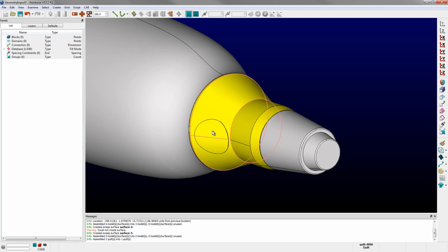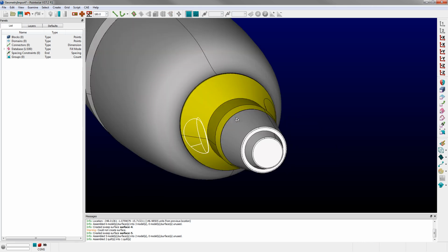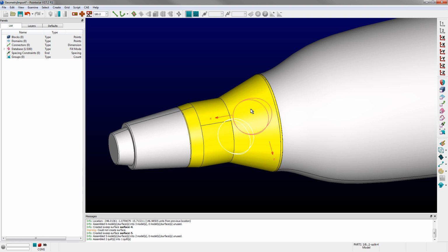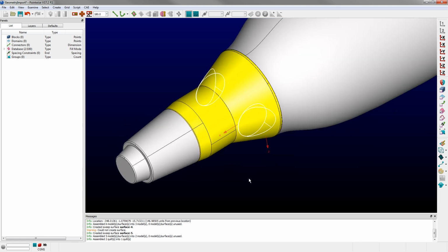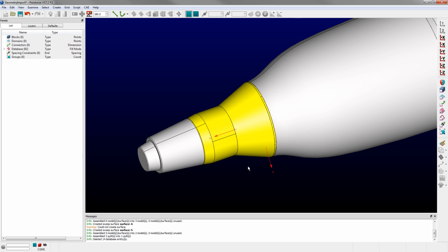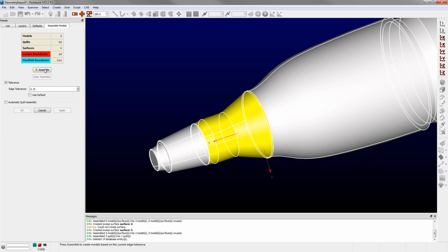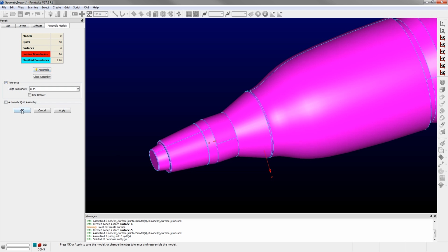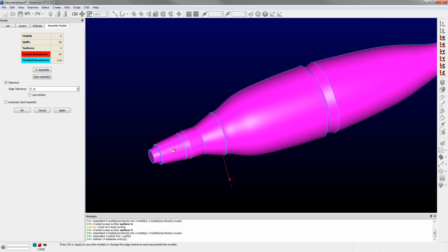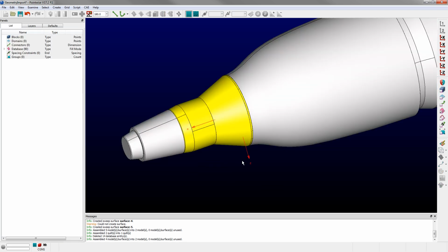And you'll notice if I spacebar through here, it's basically created a closed region on either side, two models. I'm going to delete those, get rid of them, and then I'm going to grab all my database entities one more time and create, assemble models, and click Assemble, okay, to basically add it back to the model definition. So I've essentially removed those holes from the model.